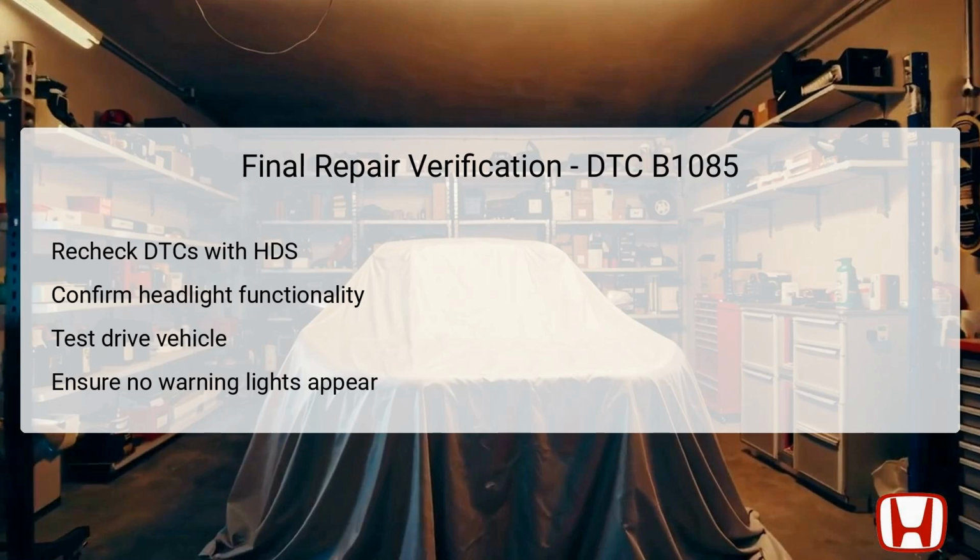Using the HDS tool, technicians should recheck for any outstanding DTCs and confirm that none reappear, indicating successful resolution of the issue. Next, it is crucial to test the functionality of the headlights to confirm they are illuminating as expected. Moreover, a brief test drive should be conducted to ensure that the vehicle behaves normally while on the road and that no dashboard warning lights are triggered during this process. This comprehensive verification step not only confirms repair success, but also allows the technician an opportunity to address any lingering concerns that may not have been evident during stationary testing.